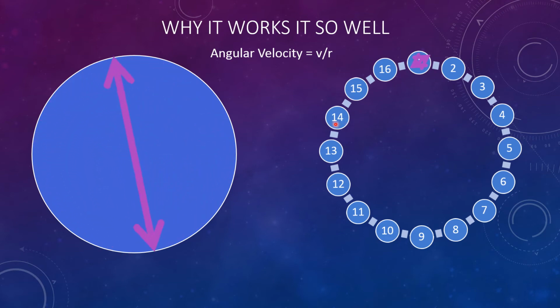So if we think about that, and let's change it to a dot, and let's show that solids moving around the outside. Here is the speed in the current offering, and basically we could separate a 74 micron particle or 200 mesh particle. But now if I do the same thing, look at how fast I'm able to move a smaller particle and separate smaller and lighter particles.